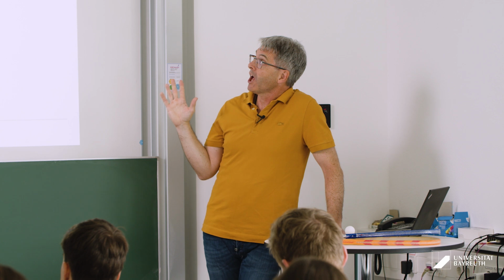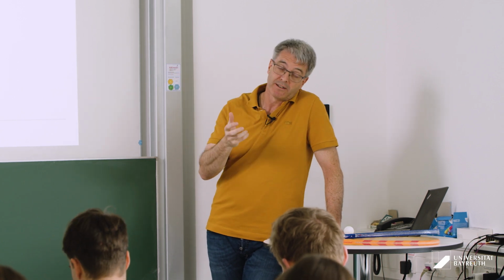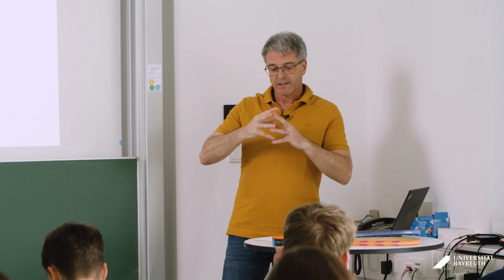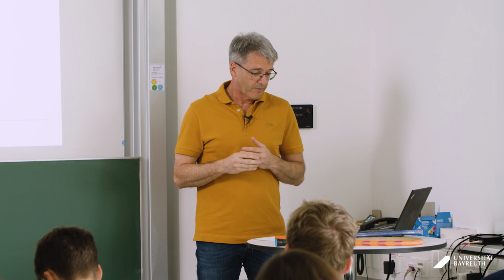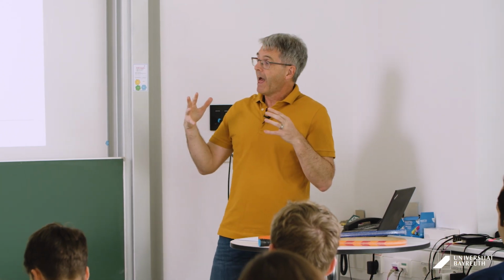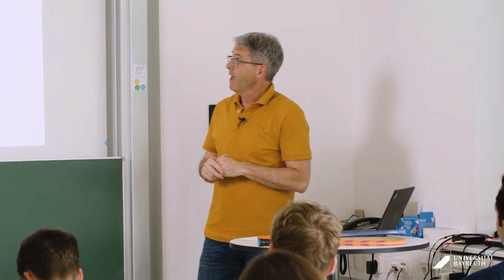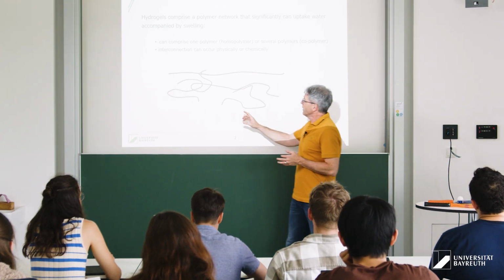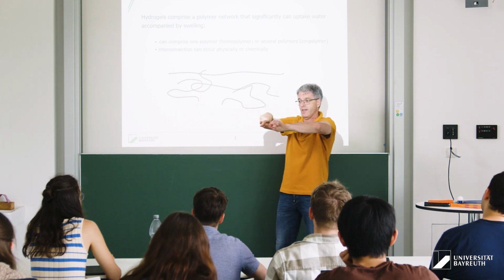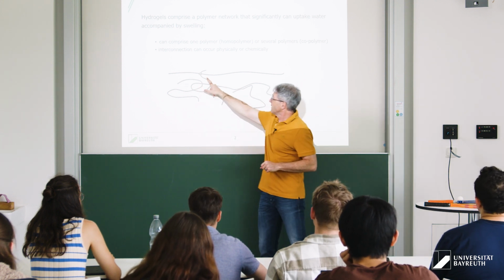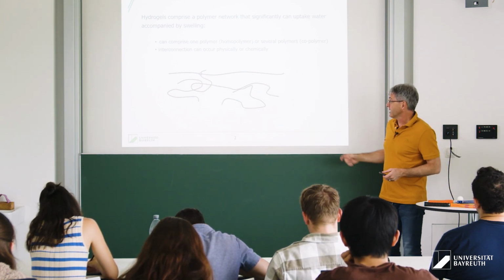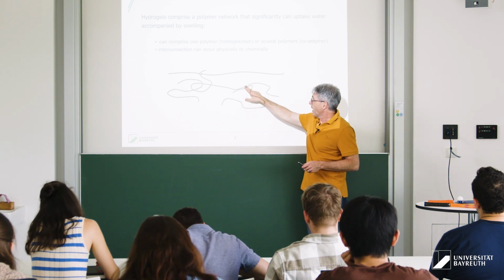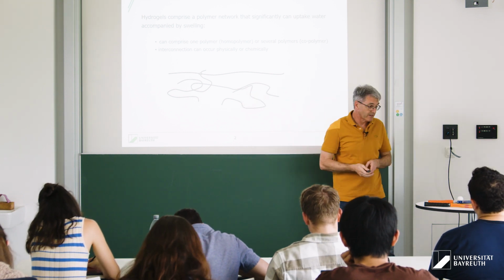So the question is, how can you keep these polymer strands in place? When you have this mesh, this network of polymer strands, and now the water gets in, and we will have a look at that in a minute, how can you place these polymers so that the water does not disrupt the entire structure? So the interconnection can occur either physically, you see here some kind of entanglements. It can occur chemically, so some knot points where you get some chemical interaction, and you can have some physical-chemical interactions like hydrogen bonds that actually make such a network strong.